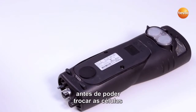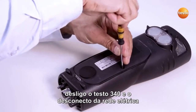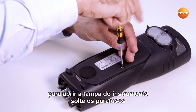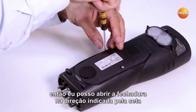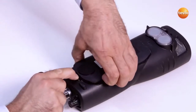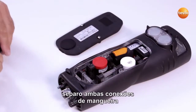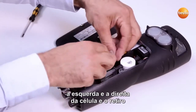Before I can replace the sensors, I must switch off the Testo 340 and disconnect it from the mains. To open the instrument cover, I undo the screws. I can then open the clip in the direction of the arrow and remove the service cover. I pull out both hose connections on the left and right of the sensor and remove it.